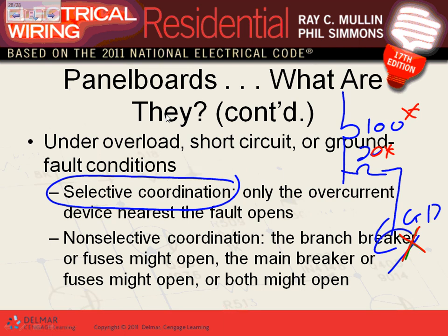And selective is great because it localizes, sectionalizes the faulted part of your system. A short circuit right in this light right now, go short it. It should take down the branch circuit that feeds this. It shouldn't take the switchgear down. You would hope so. That's why we do a ground fault. That's why we do the overcurrent protection coordination, which you, my friends, will be doing with your friend Chad in the industrial project for sure.